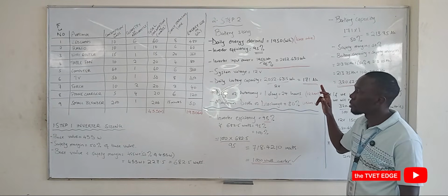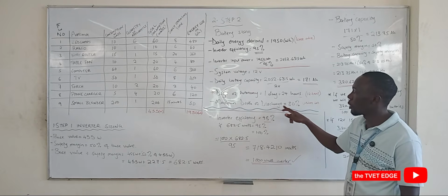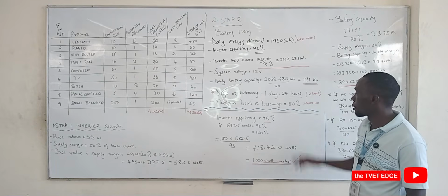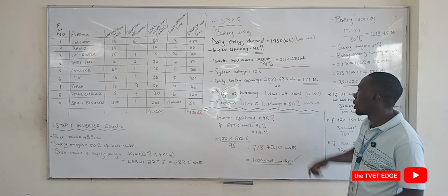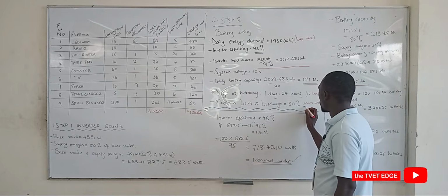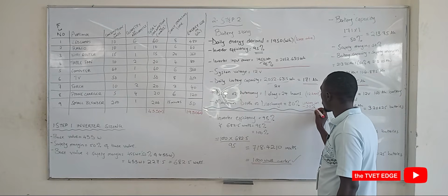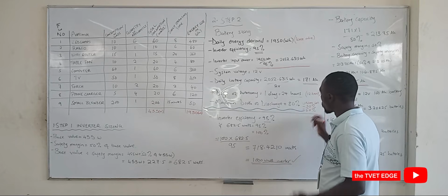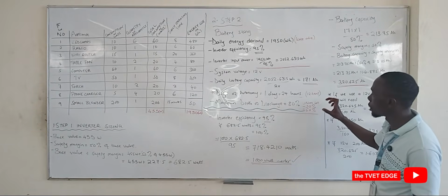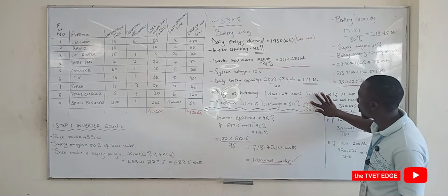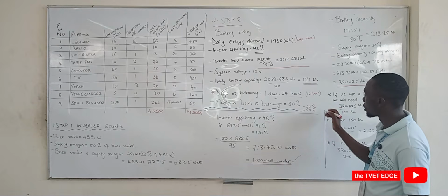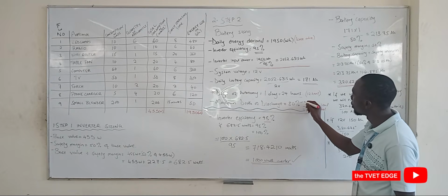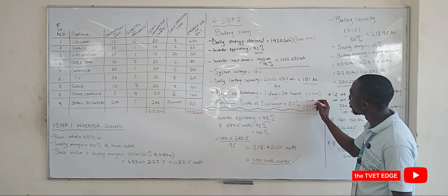If we do this same calculation, but instead of lithium ion batteries, we use lead or gel batteries, this 80% value will change. And for lead, we have said we will be using 50%, and for gel, we'll be using 60%. So this is the maximum amount of charge that you can take out of the different batteries. So this is lead, this is gel, this is lithium ion.